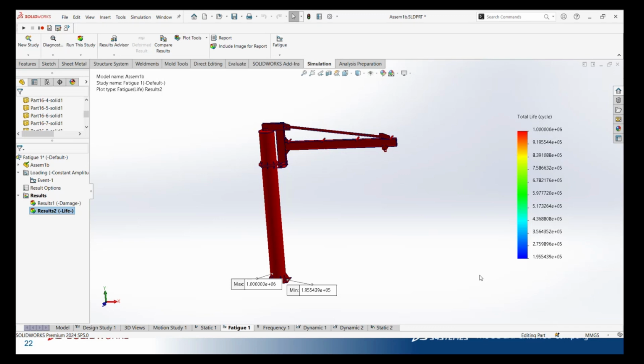Yeah, it will also indicate the wear and tear. For example, if you use it for 10,000 cycles or 20,000 cycles, how much damage percentage of the jib crane has happened. So all these things we can also analyze with this fatigue analysis. As I told, the fatigue analysis takes the results of the static analysis and, taking the values that we have added in cyclic, gives us the results based on that.